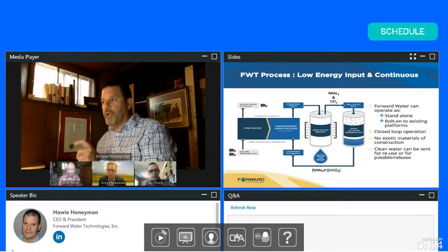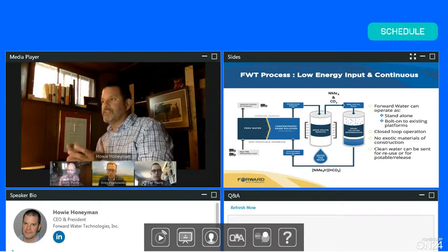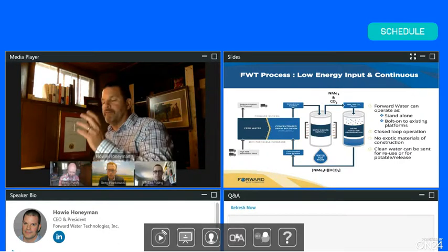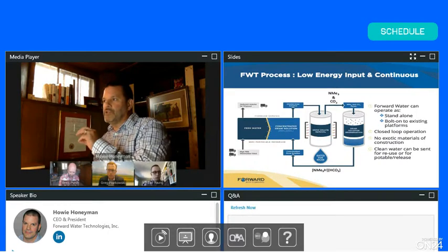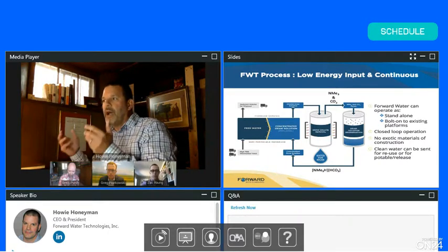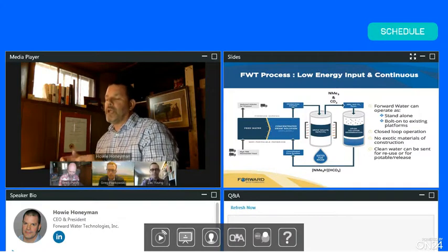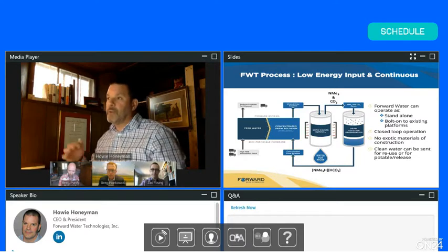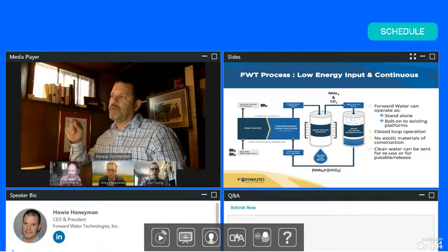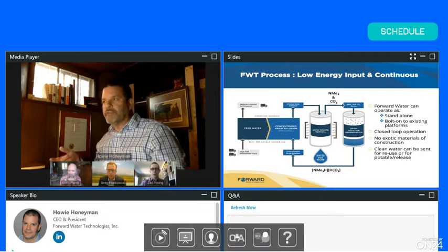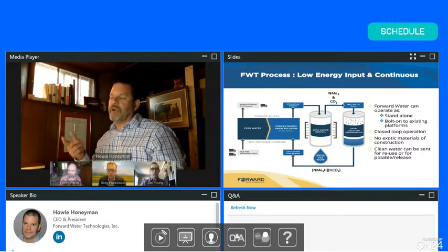So we've got no applied pressure, but we're extracting the water through the membrane. Ultimately, once that solution is exhausted and has reduced the volume of the feed water, the feed water goes off for final disposal, and that now diluted draw solution gets processed by a little bit of heat being pumped into it. That causes our proprietary draw solute to turn into two gases, and they simply bubble out of the now clean water, leaving behind water that can be sent straight for reuse. And we capture those evolving gases, reconcentrate them in a second step, and reuse them in the front end of the process.